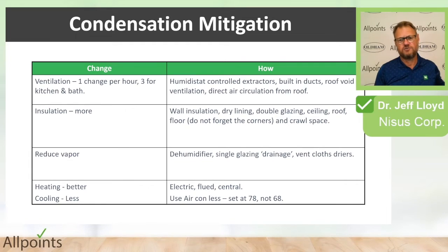You can also see black stripes on the edge of carpet sometimes where the carpet goes under the kickboard. That's typically where you've got moisture coming from the crawl space and meeting the cold air at the floor from the HVAC system, and that will grow mold around the edge of the carpet and give you a black edge to the carpet.